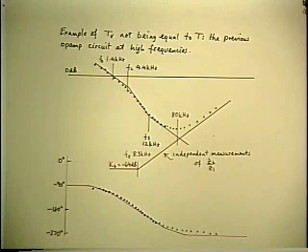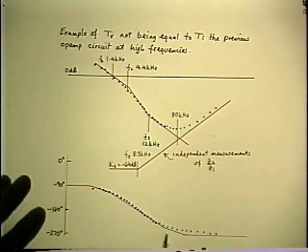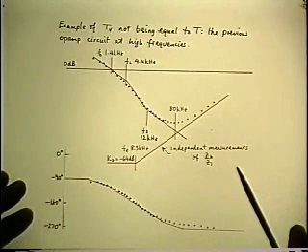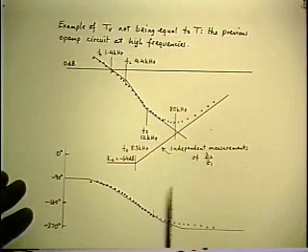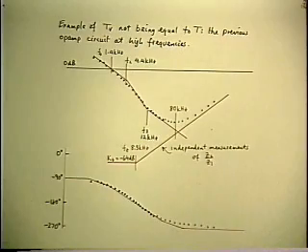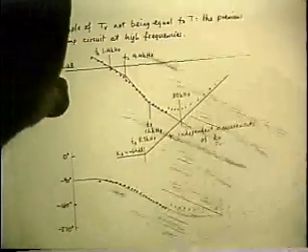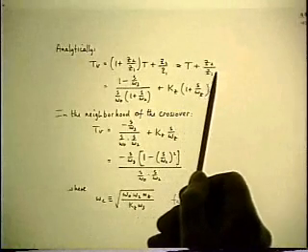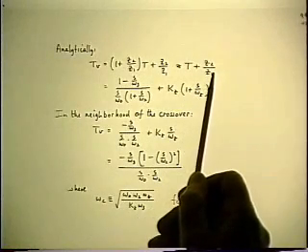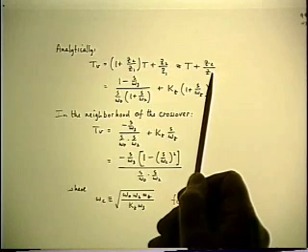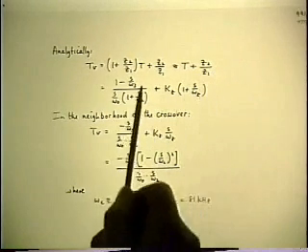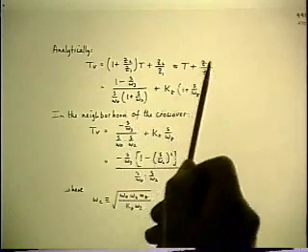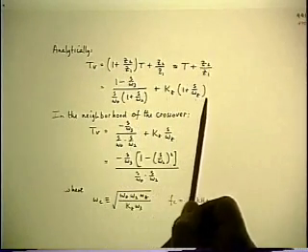But we haven't quite followed up everything yet. Why wasn't there a change in the phase? So let's look into that. So we're starting now to look into this question. We want to add these two functions analytically and see whether it predicts the phase that we've actually measured. And so now T is this expression, including the right half plane 0, and the impedance ratio is that expression.